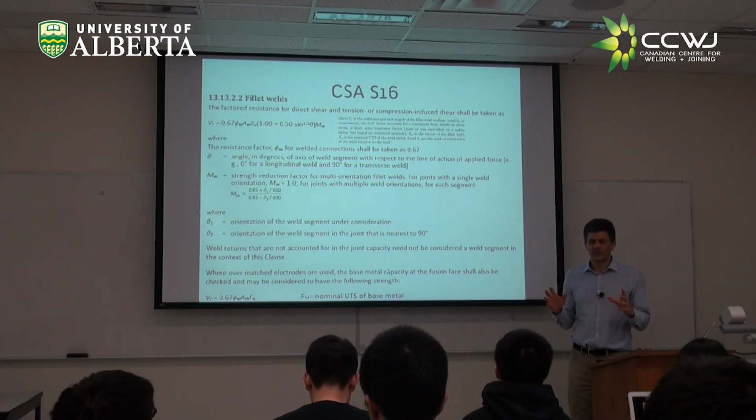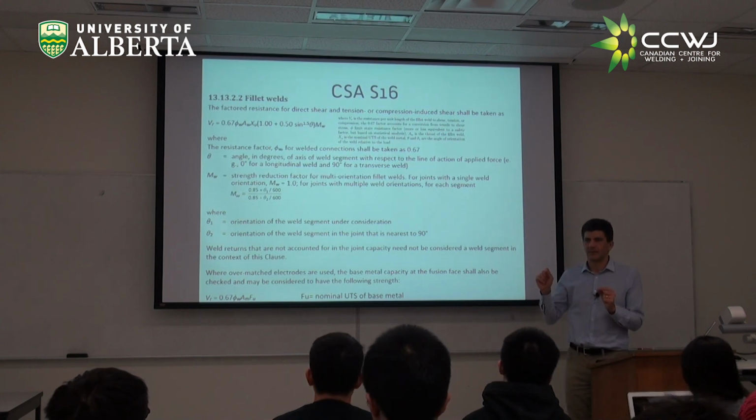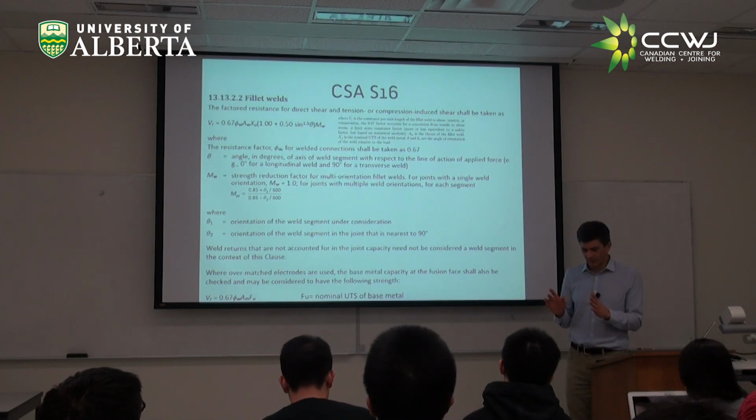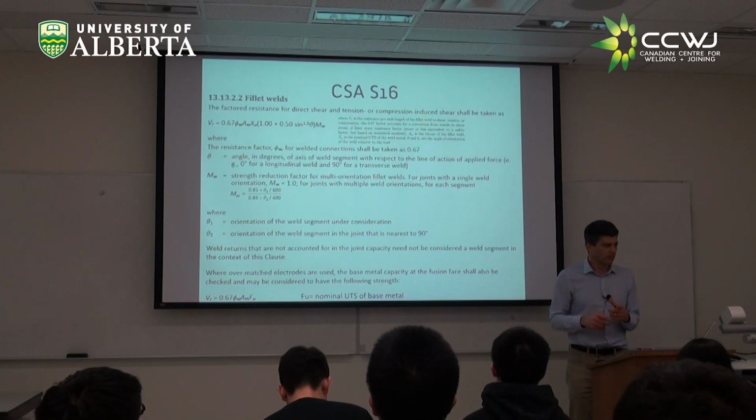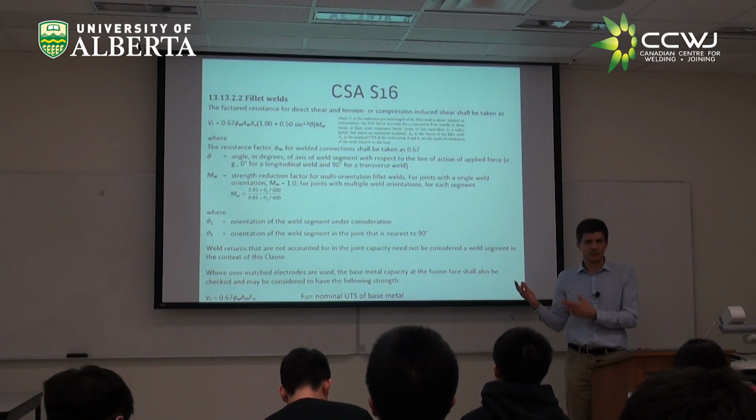The central concept to this calculation of welds is assuming the weld is just a line, right? We assume that the weld is just a line, and this line has a force per unit length. Of course, a weld is not a line. A weld has a size, right? We're actually going to be calculating the size of that weld.